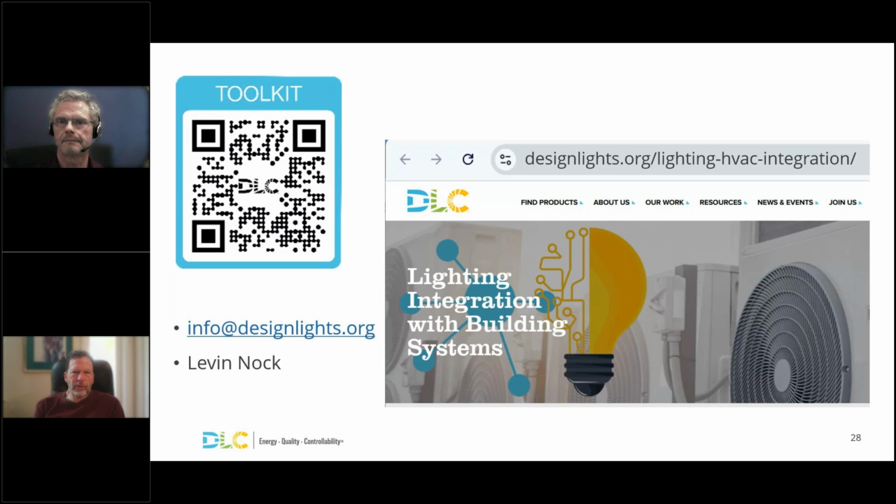Well, the short answer is absolutely yes. Anytime you can adjust the performance of the HVAC system by knowing when and where people are, and I go on beyond just occupancy, but occupancy and density of people and duration of people in spaces all leads to some very good performance metrics that can be used to adjust the schedules and other parameters in the HVAC sequence of operation. So they can be measured.